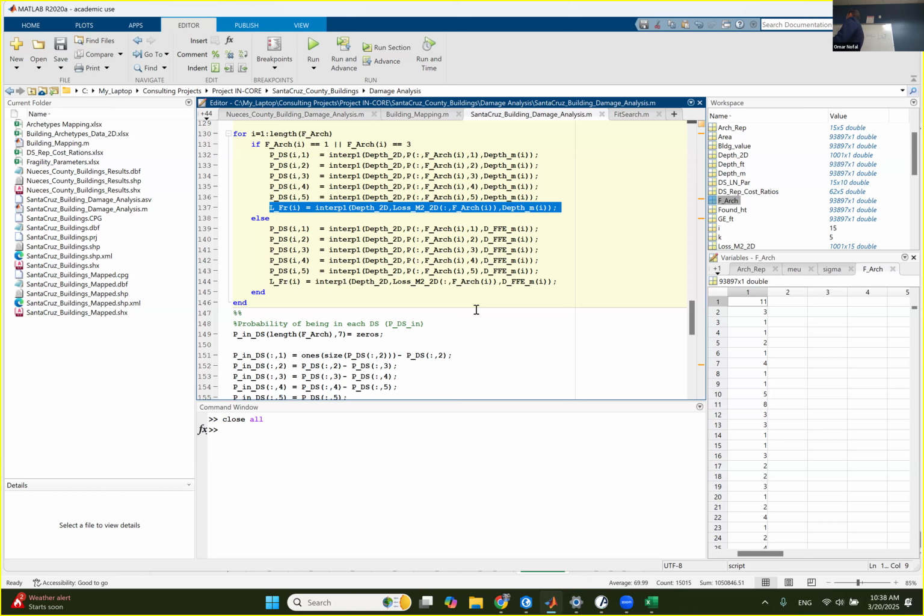So how can I calculate from exceedance probability? Exceedance probability is, in a different color, that's actually what we got from this curve. Like all the numbers here, this is exceedance probability. What does it mean? Let's say here, if you wanted the exceedance probability of damage state 1, it goes all the way up and tells you what this whole value is. But we don't need all this value. We only need this from here to here. So you need to find the value here and the value here and subtract them to get this value. So that's what I'm gonna do next step.